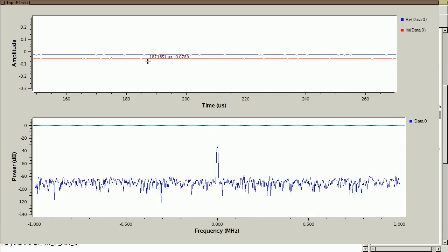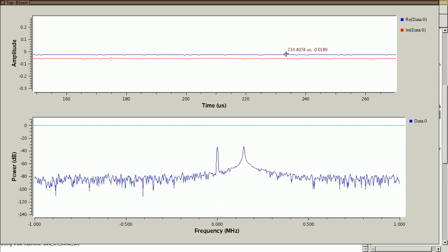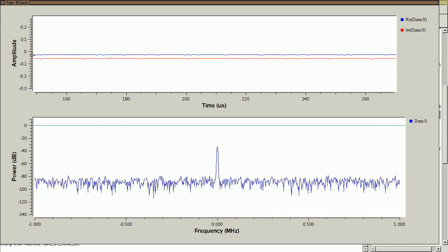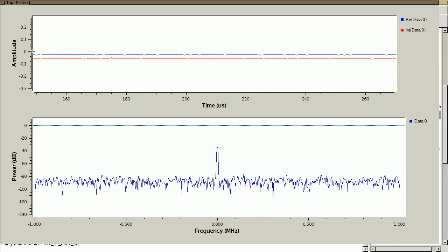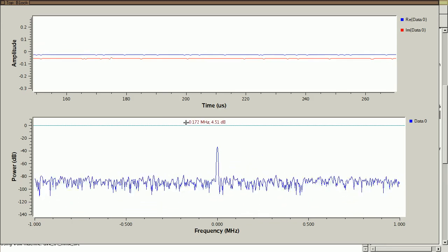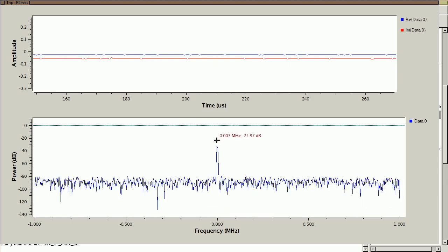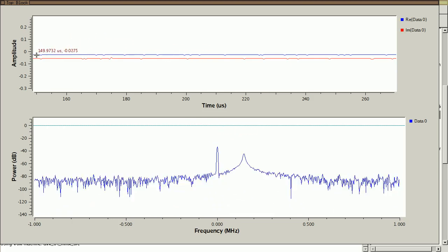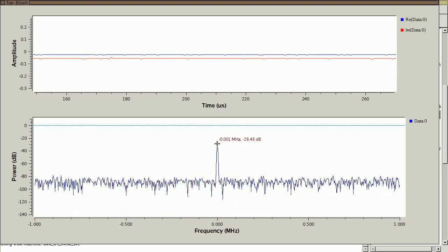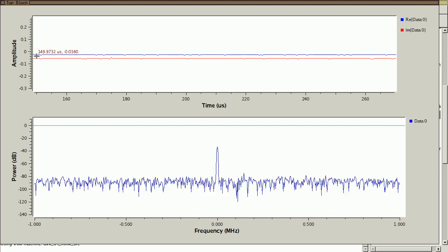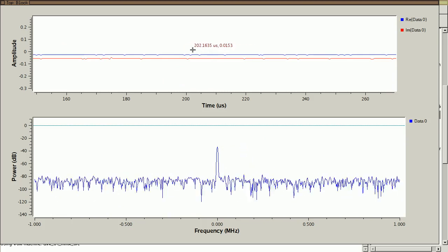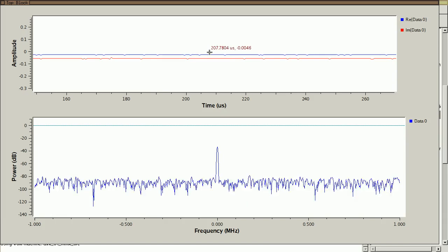And inspect a little bit this background noise here that happens between bursts of activity. Do you see how everything's between 0 and negative 0.1? It's offset from 0 a little bit, which is no big deal, but that's an explanation, and we'll talk about this later in a little more detail perhaps, for this 0 hertz spike in the middle. There's some portion of the signal all the time that is a little bit off from 0. And that's perfectly normal in a receiver like HackRF to produce that type of a small defect.